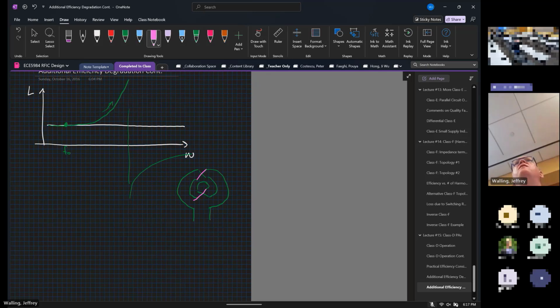Just had a question regarding the center tap of the inductor. When you make an inductor with a custom design in the PDK, why can't we use a lower metal even for a center tap? I know the downline is lossy here, but when you have a center tap, it is always fixed, right? It might have some IR drop because of the resistive loss. Well, if you draw your own inductor, you can do almost anything you want as long as you follow the design rules. I'm just saying, in literature, we never see people using a lower metal layer for it.